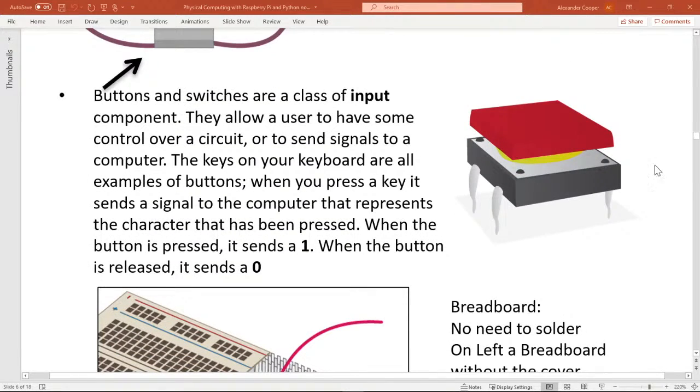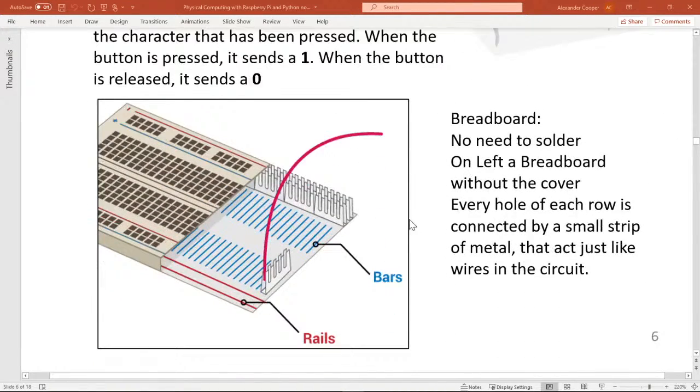So here's a tactile button that we have, and this is talking about our breadboard that we're going to be using. Big thing about our breadboard is this has it split off, and I always want to show this. There's rails, okay, so you can plug something in here at the top of the rail and then have something else down here, and they'll connect. But if you use this like a vertical rail, and these are like the horizontal rails, and then there's like a river in the middle, so there's nothing that connects from one to the other, okay. But these rows here is where you plug in something here on the same row, plug in something here with the different holes there, and then they'll be connected, okay? So instead of us having to solder wires together, we're going to use our classic little breadboard for our projects, okay? So projects with no soldering required.